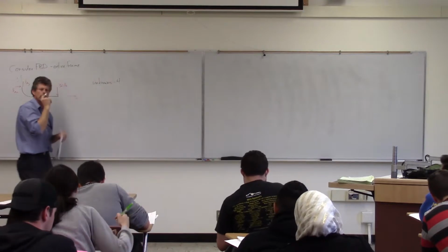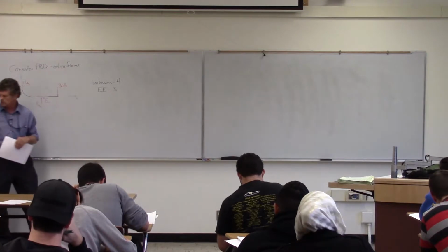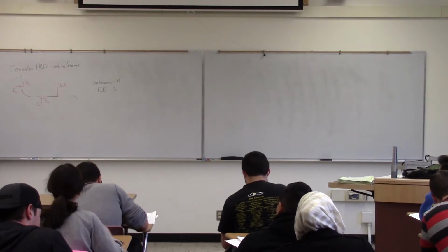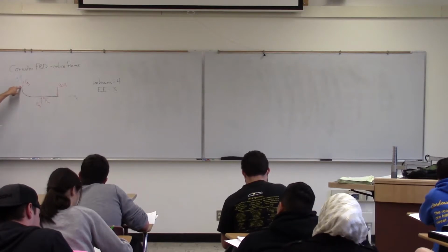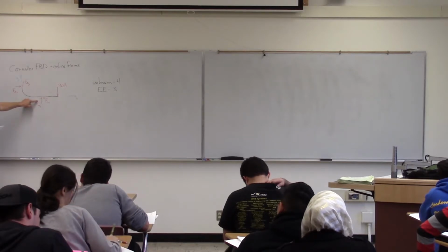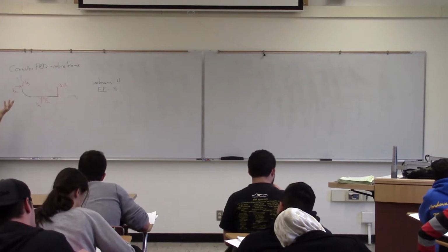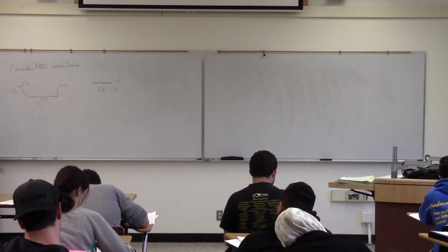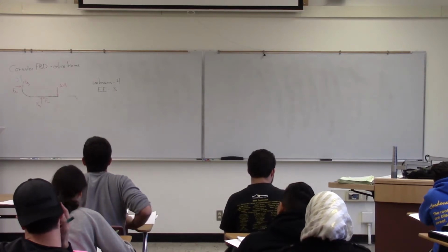And there's nothing really tricky we can do. Equations of equilibrium in 2 dimensions are only going to be 3. Now, I can't even do that trick like we did with the earlier one, where I did a moment equation to get the y component. Because if I took a moment equation here, I eliminate the y and the x, but I have an FCy with a moment arm, and I have an FCx with a moment arm. So I've got 2 unknowns there. I sum forces in the Y direction, I've got 2 unknowns. I sum the forces in the X direction, I've got 2 unknowns. So that's not going to help me. I only have those 3 equations, but I still have 4 unknowns.